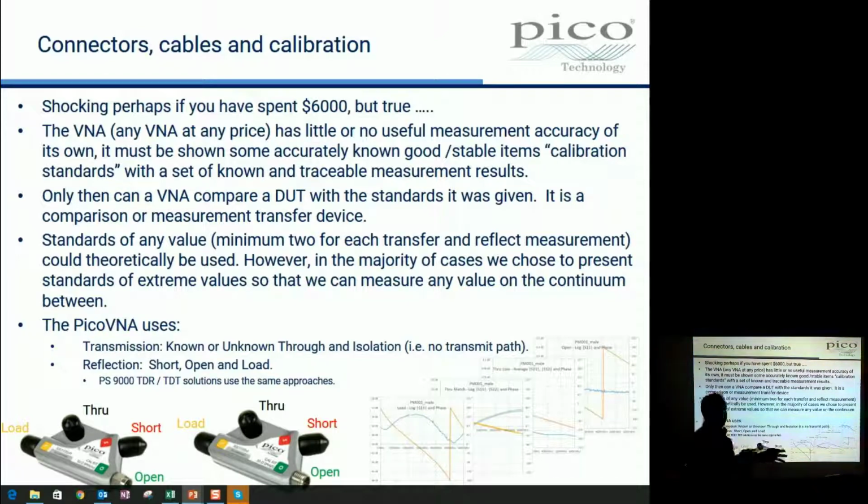We're really focused on a particular impedance, Z0, the characteristic impedance of the VNA and all the measurements that we're going to make, 50 ohms. So it's handy just to have a load, essential actually. We need a precision measurement of what 50 ohm looks like. Well, not precisely, but pretty close, provided with a data set that says how close we are.